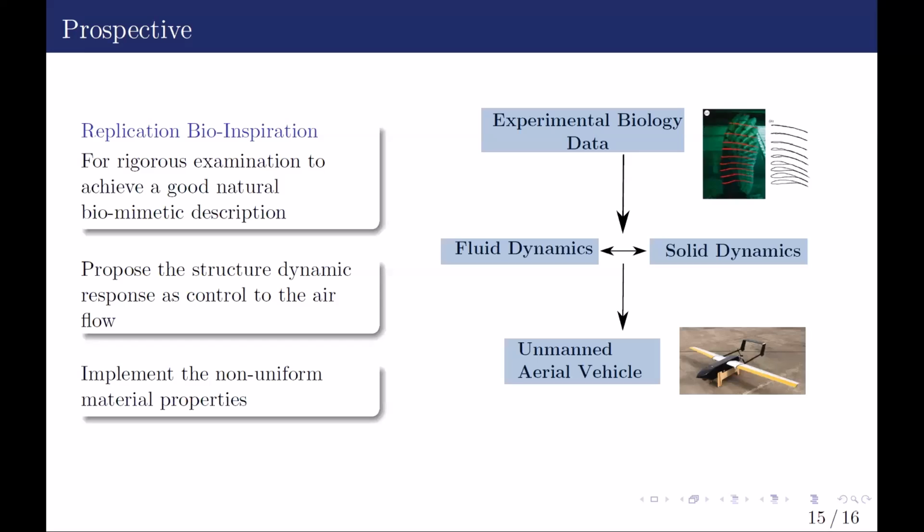Could you explain a bit about the dynamic response as controlled? Are you trying to do soaring or something? So this is actually the step that comes after, when we do the dynamic simulations. Dynamic simulations will allow us to see the response even after the solid has deformed. We go back and feed this displaced mesh from the solid to the fluid. So this way, what we call two-way, we will solve iteratively in a two-way. But what the data I have shown now is a one-way. Is that answering the question?